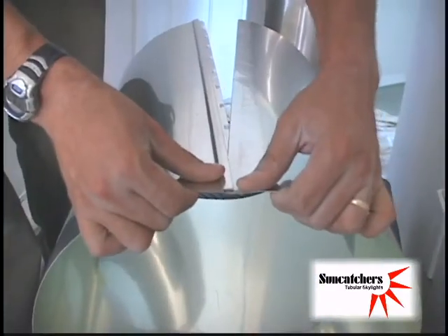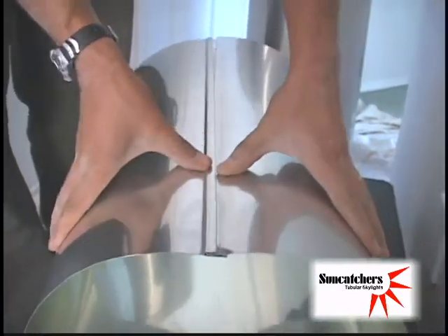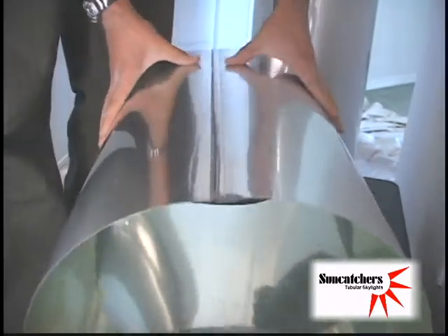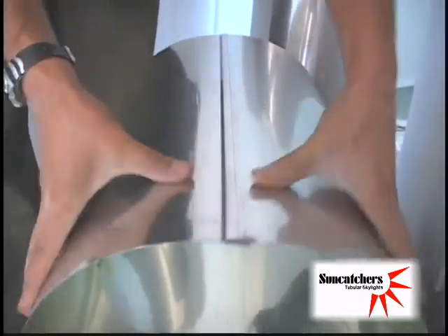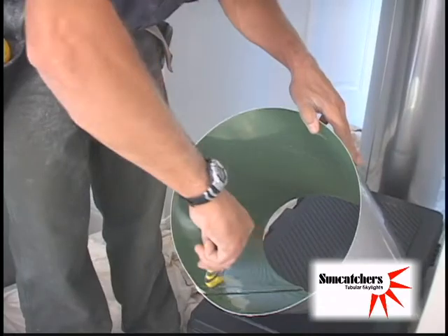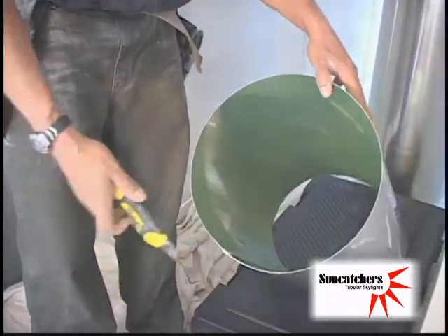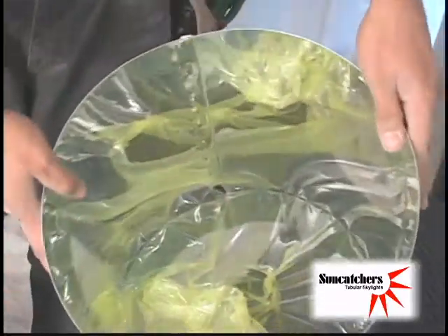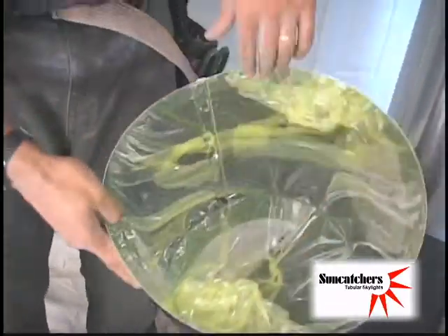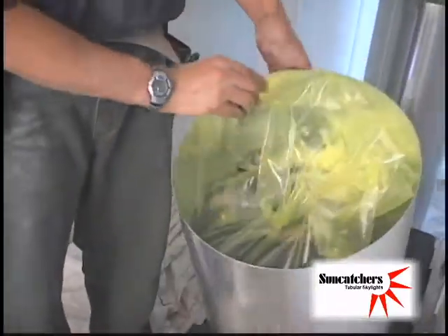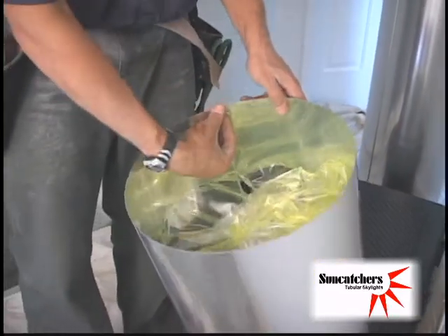Lock in the seam of the pipe by pressing the edges together from one end to the other, ensuring they are completely clicked together. Using a utility knife, score along the inside of the seam and peel the protective film halfway down the pipe. Flip the pipe over and peel the film down approximately 2 inches.